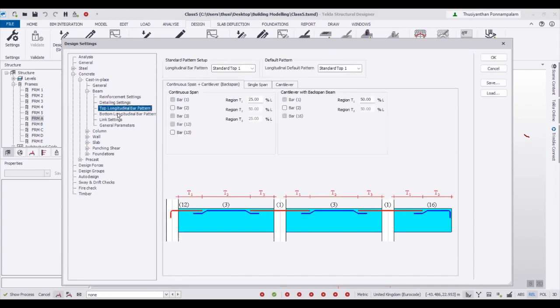Okay. Then top bar arrangement. Basically, this arrangement may look strange, right? Normally, when you go with the Concrete Institute code, we may not need to do this kind of curtailment, right? But for easy purpose, this software is using this one, right? That's what we get to understand. If you want to change it, you can change it on your own. Later I show you how to export these results. After you export the results, basically you can modify all these rebar based on your own requirements, right?